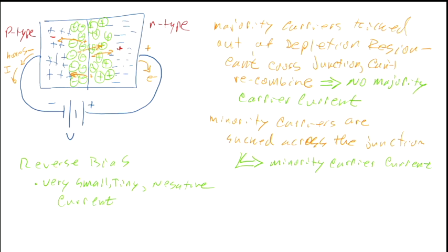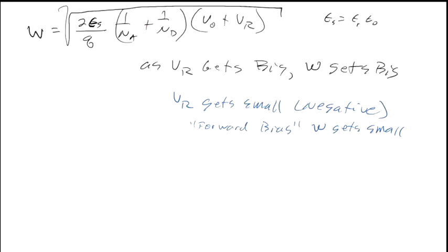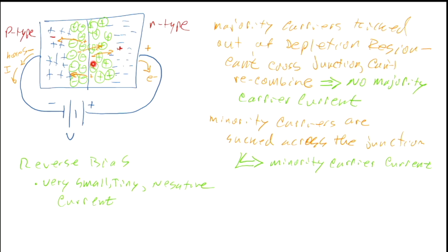So there was a question about the last slide. And this is reverse bias. So the depletion width gets bigger if we apply a more negative voltage on the p-type side than the n-type side, and current is squeezed down. It becomes less. And there's a handy equation for that, the diode equation, or the Shockley equation.